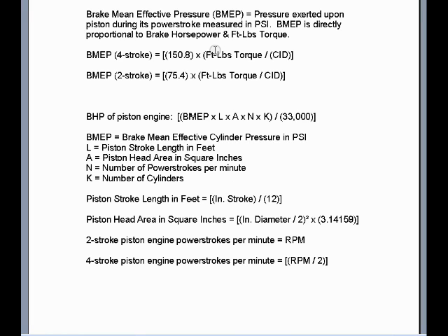Brake mean effective pressure. This is the pressure exerted upon the piston during its power stroke, measured in pounds per square inch. BMEP is directly proportional to the brake horsepower and the foot-pounds torque output at the engine's crankshaft.